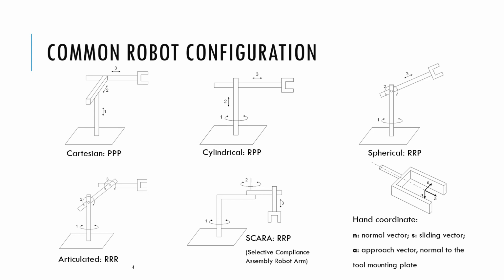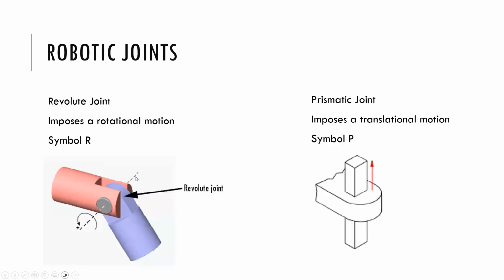So even when I'm doing a rotation joint, this is usually my Z-axis in most robotic systems, because that's the axis that allows the degree of freedom to happen. So that's where the Z-axis is the most important, and the X is the second, and the Y, we kind of just take whatever happens. And if it's prismatic, I'm going up and down, so my Z will either be going up in the air or down, and that will allow you motion in that direction there. It could be inverted as well, and it still meets the criteria. And this could be going into the page or out of the page, and it's still going to resolve that.